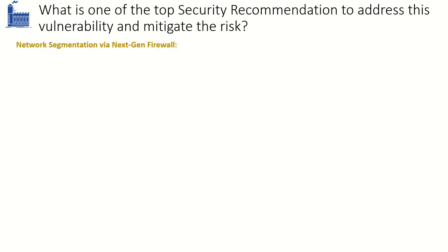So, what are the security recommendations for the ICS environment? The standards give a lot of security recommendations. There are different standards available for industrial environments by different companies, by different bodies in different countries. We will not be discussing all those standards, but rather one top security recommendation which is there in every standard to address the vulnerability and mitigate the risk of unpatched devices, which is network segmentation via a next generation firewall.